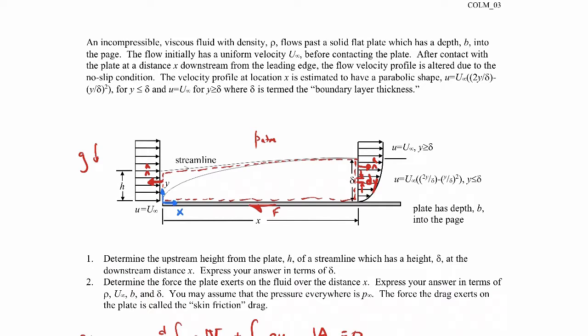Now, as far as viscous forces in the x direction, well, the vertical parts, there are no horizontal components of viscous forces there, so you don't have to worry about that. Along the top, the dashed line here represents the transition from where you have no velocity gradient to within that little dashed line where you do have velocity gradients. Since the top of our control volume is outside of that, the velocity gradient along that dashed line is zero, right?